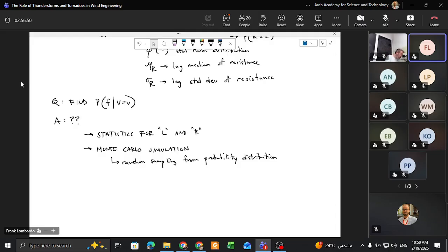For example, I'll give you an example in MATLAB. A lot of times in MATLAB, the function looks like this. It'll have some distribution identifier, GEV, which is generalized extreme value, then RND, which means you're going to randomly sample from that distribution, and then you list your parameters. In the GEV, we mentioned that it has 3 parameters. You give it those parameters, and you also give the length of data that you want to sample. Then you randomly sample from that probability distribution, and you would get different values.